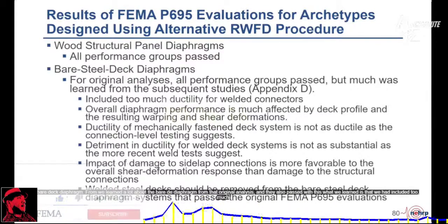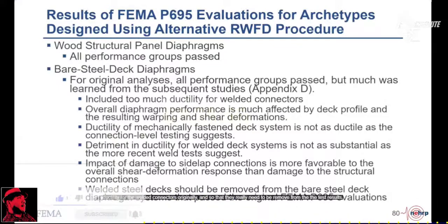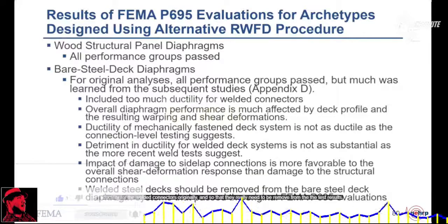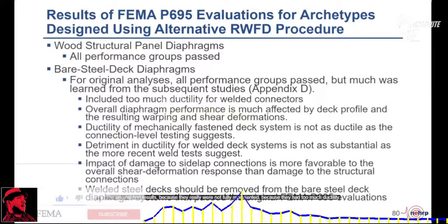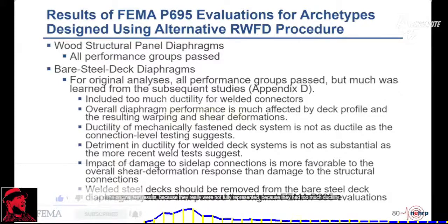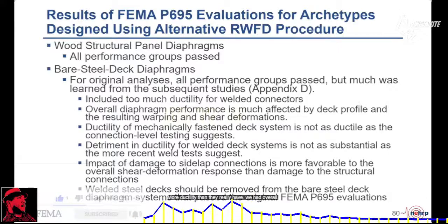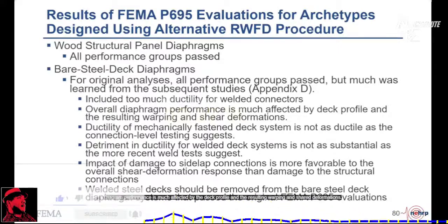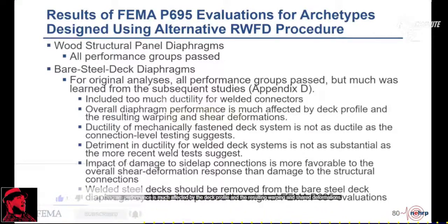What we learned is that we had included too much ductility for the welded connectors originally, and so they really need to be removed from the original test results, because they were not fully represented, having more ductility than they really have. Overall diaphragm performance is much affected by the deck profile and the resulting warping and shear deformations.